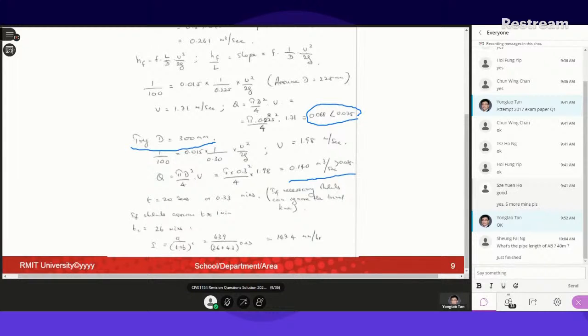So we get the intensity. We can get the intensity from the table or from the equation. Here you can get it from the equation, because there's no 25 minutes intensity in the table, so you can use the equation.